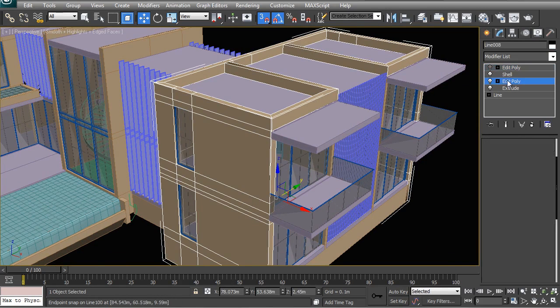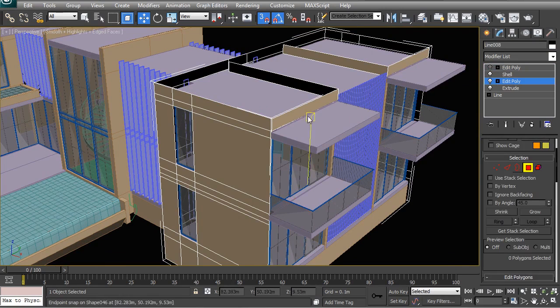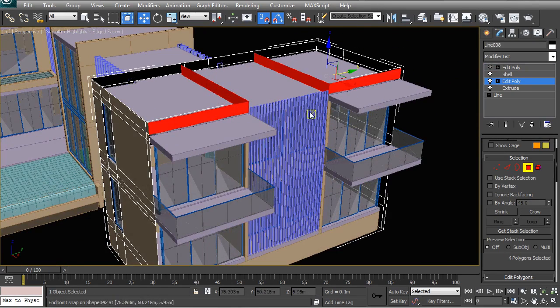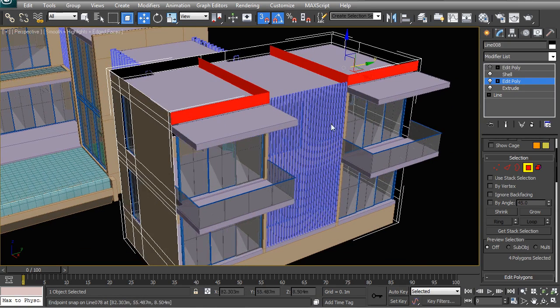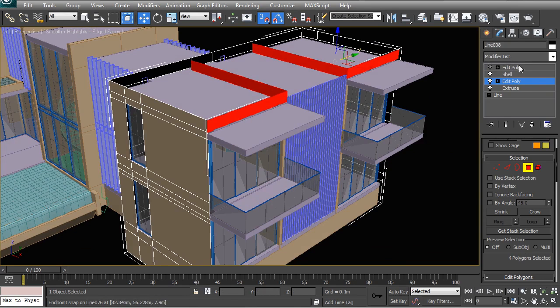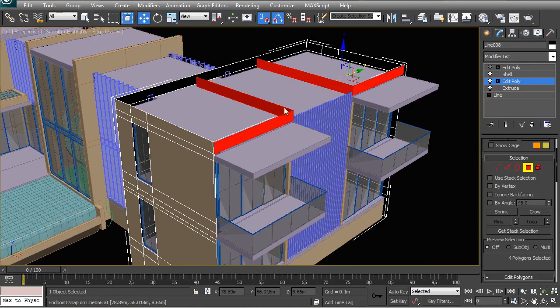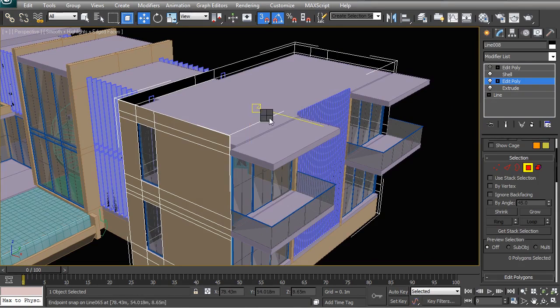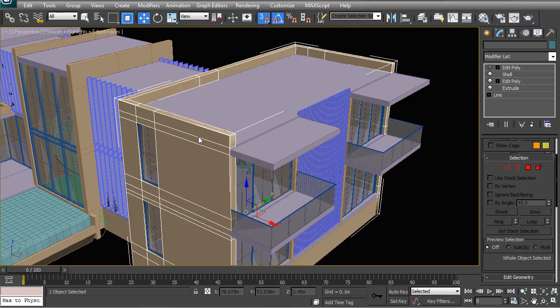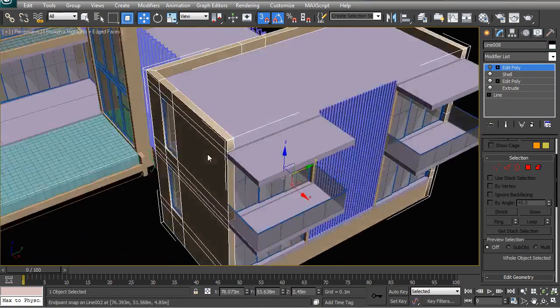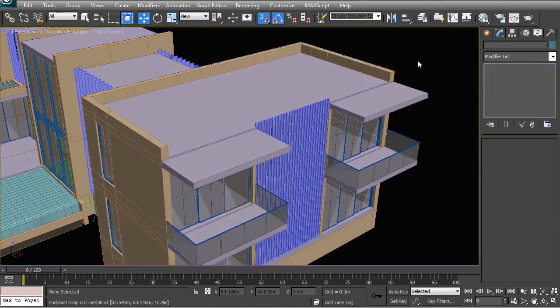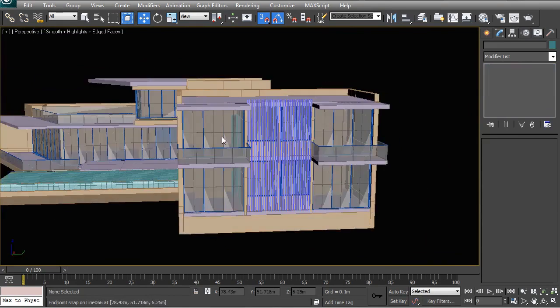So I'm going to go down to the editable poly where I can still work on the model without affecting it in a bad way. In other words, I won't have anything destroyed once I activate this top editable poly, since this one just removes my smoothing IDs. And with those 4 polys selected, I'm going to hit delete on my keyboard, and once I'm at the top level, then I have a much neater shape, and I'm a lot happier with this. Just turn that on again, and we can then just have a look at what this looks like.